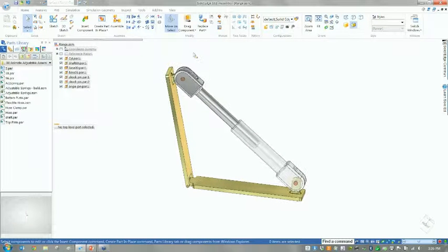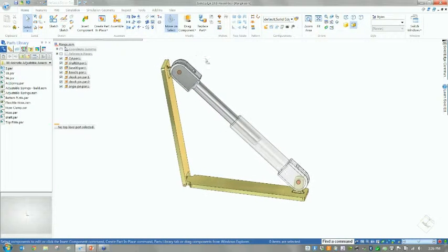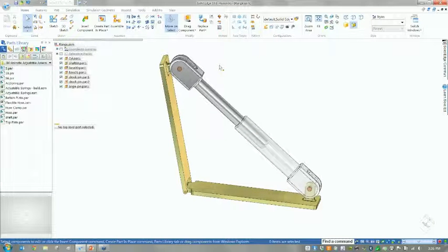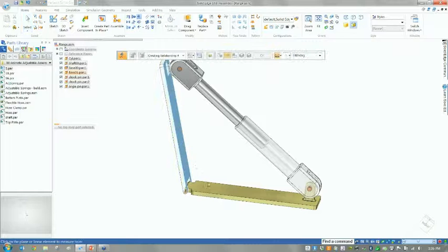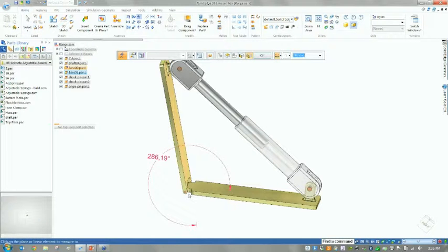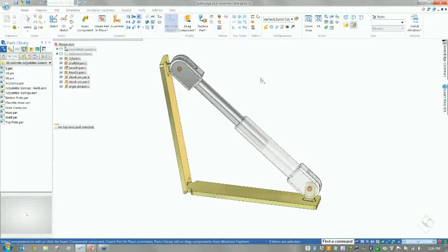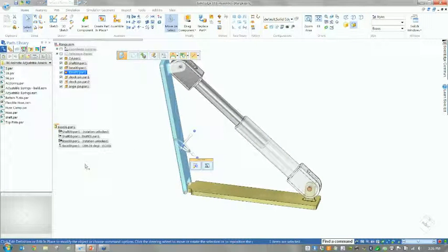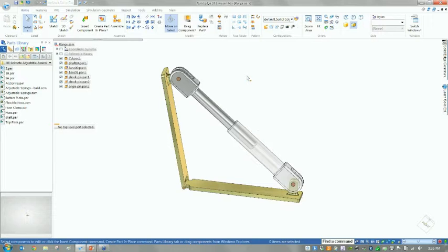It didn't realize that range was still flexible. So in ST8, that's been relaxed, so we can actually do this. We'll simply say I'd like to put an angle between here and out on this face, and say okay and have an angle relationship. As we look at that, the angle relationship is 286 degrees. You can have it any way you like, but that angle is 286 degrees.